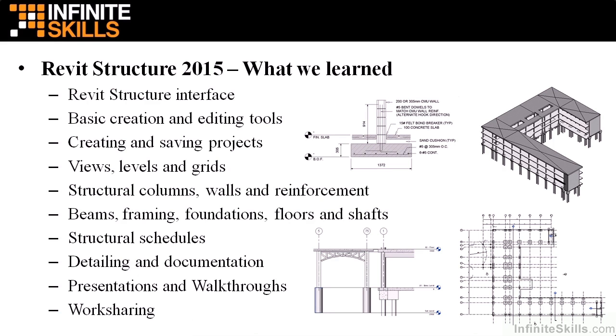From there, we went on to create structural projects. We started with a standalone project, and then we linked in multiple Revit projects or models to our Revit model. We talked about monitoring changes between these models, and we talked about review messages, information, if you will, if something is out of date or updates are out of sync.